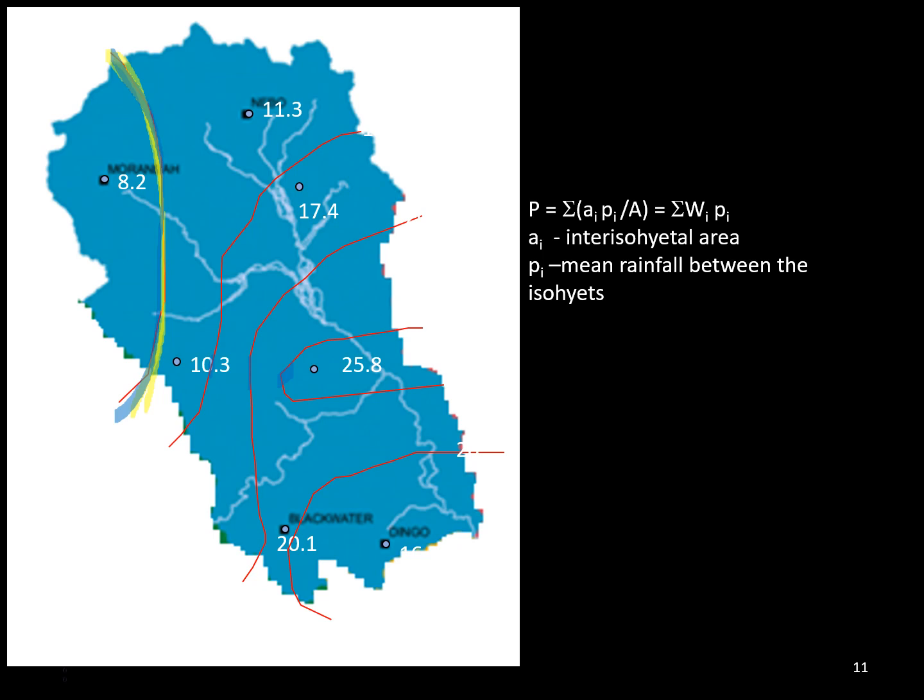Similarly, here between 11 and 17, there is only one, which is 15, and then you draw this line with 15, right? And this way you draw a contour. So it's like in surveying. If you have already done surveying, you know how to draw the contour. Otherwise, this contour is applicable in rainfall estimation as well, to draw the rainfall of equal depth.